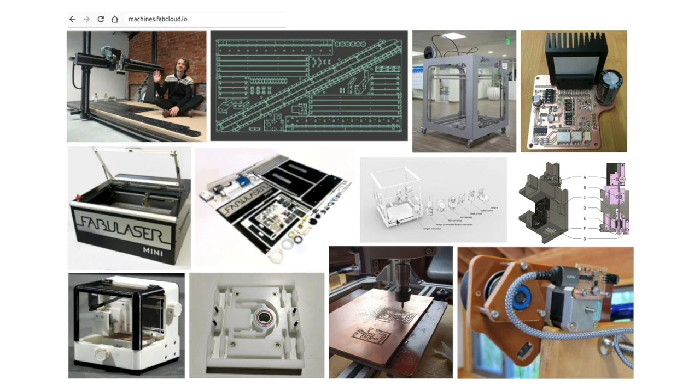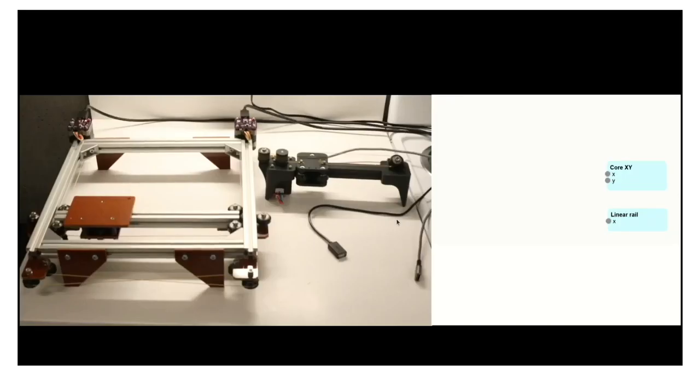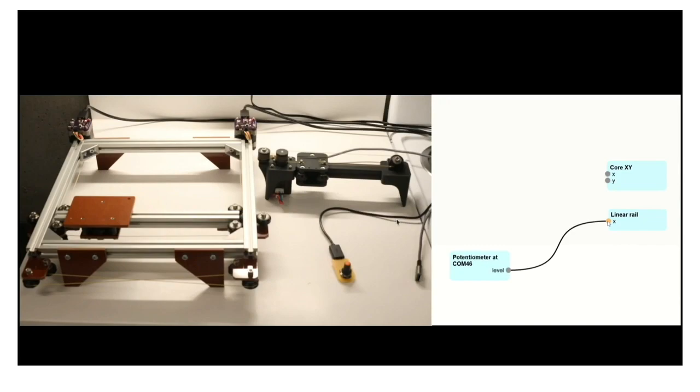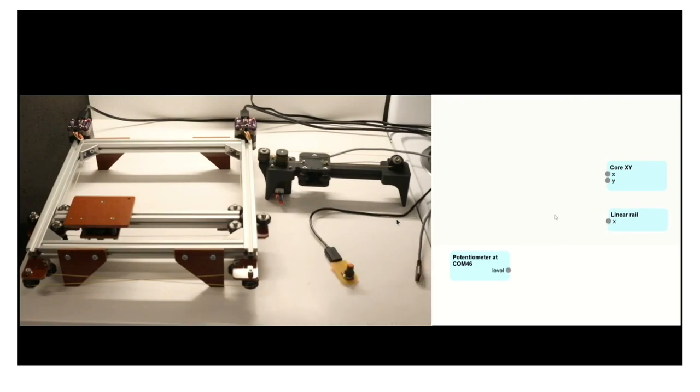So one of the things we do is G-code, and anything like that is the enemy, because it enshrines a historical division of labor. And if you want to change anything in the machine, you need to change the machine's configuration. So instead, what we do is we take the leaf nodes in the network, every motor, every actuator, we connect them in real-time networks, and then we build virtual data flow controllers over these real-time networks. So the machine is stateless.